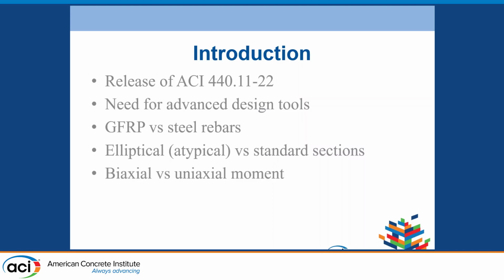Another challenge is the biaxial moment. Now, this is also available in current software for conventional concrete, but the reason I'm mentioning it here as a challenge is that for elliptical sections, moving from uniaxial to biaxial complicates the problem several folds in comparison with standard sections like rectangular and circular sections. Plus, there's a lack of literature about elliptical sections specifically, on how to tackle the problem from a formulation point of view.